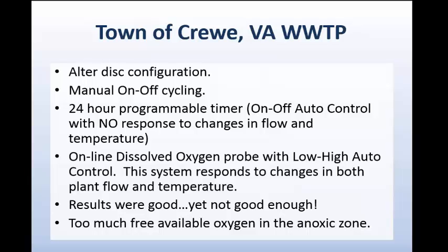So we went to the next step, and that was we installed 24-hour programmable timers that had an on and off control, but they had no response to changes in flow and changes in temperature. And with wastewater treatment, 2 very key parameters are going to be flow and temperature. They're going to drastically affect your treatment results.